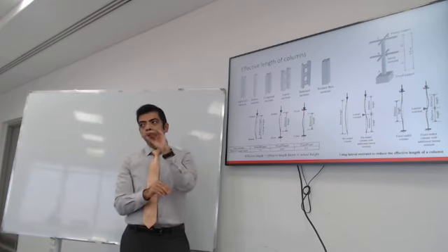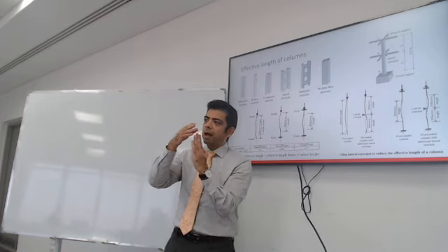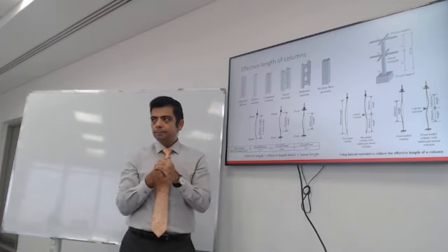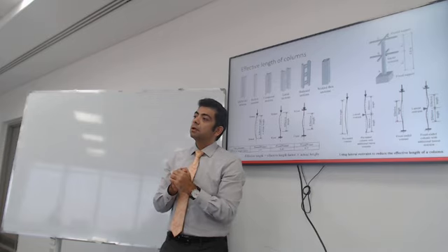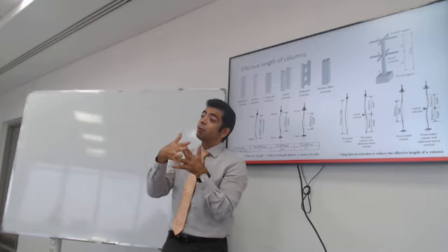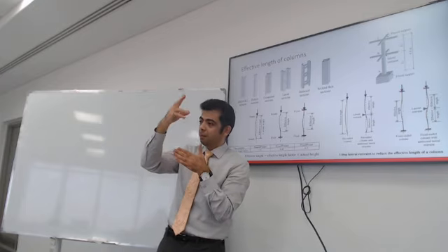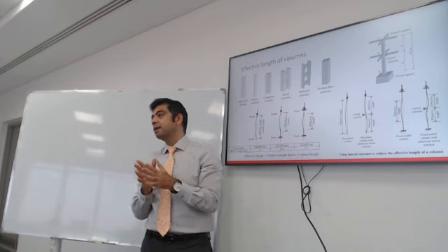So you will have to look at the connection. Where is the connection between the column and the beam? I would take it from beam to beam. Okay, I'm talking about a concrete building. Yeah, it's fixed support, right? It depends on the reinforcement detailing. If the reinforcement is developed in the wall or in the column, it is fixed. It could be designed otherwise.